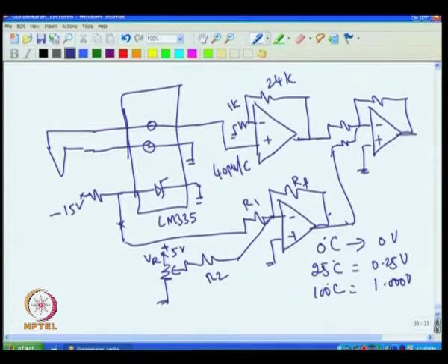So I take this, then this voltage and this voltage are added up. This gives me 1 millivolt per degree C, this gives me 10 millivolt per degree C, because the sensitivity is 10 millivolt and we have not scaled it much, 1:1. So you will get 10 millivolt. So if I put all the ratios equal, then